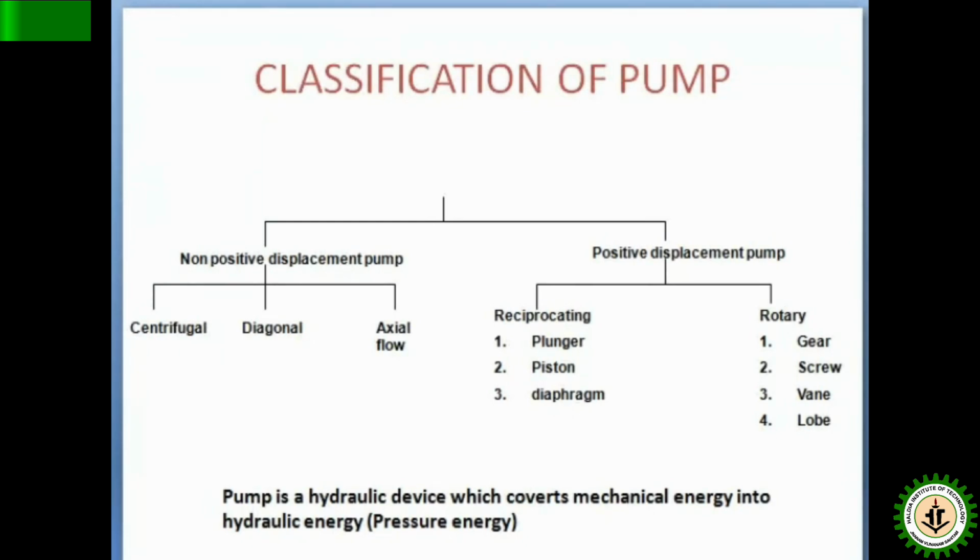So as I said, the process plan. The concept of a process plan is a combination of unit process and unit operation. You have to know unit process and you have to know unit operation. What are the unit operations? Unit operations are mostly physical operations like drying, crystallization, compression, blowing, and some heat exchanger operations. These are all unit operations because there is no involvement of any chemical reaction. And unit process means there is the involvement of chemical reaction. Chemical reaction means there will be stoichiometry, there will be kinetics.